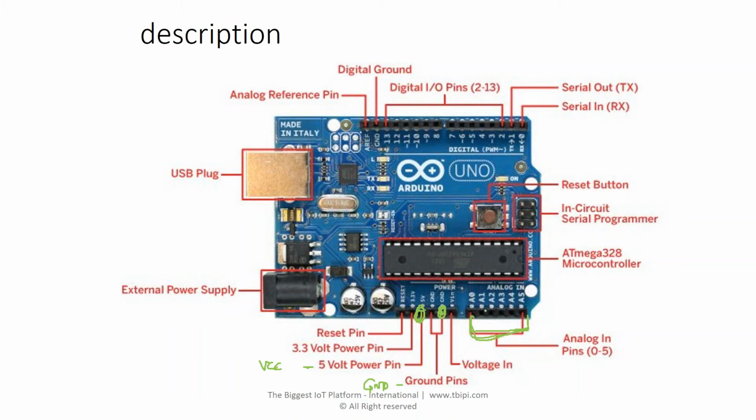We're going to connect the sensor on A0 to A5 anywhere. Let us say that I'm going to connect it on A2. We have 3 pins in the sensor. Two pins we have already connected. The output pin of the sensor will connect to A2, and we'll program Arduino so that we can see the value of the sensor. We can see what Arduino understands whenever there is an object and no object. So let's go ahead and write a program.